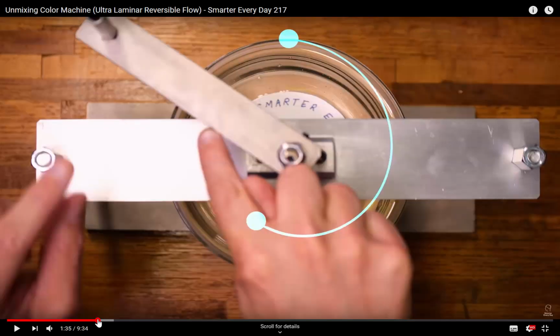He discussed the no-slip condition, how the fluid at the outside edge of the container has the same velocity as the container itself. And then same thing with this inner cylinder. The fluid that's in immediate contact with that inner cylinder has zero velocity. And so the further away you get from either of those two surfaces is where the velocity is the greatest. Since he was rotating it really slowly, the Reynolds number stayed low enough that none of the radial layers were mixing with each other. And so there wasn't mixing outward radially.